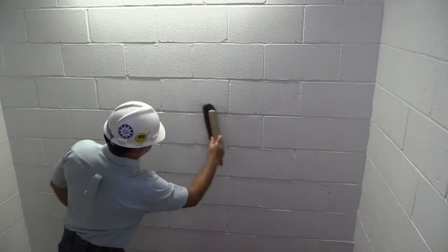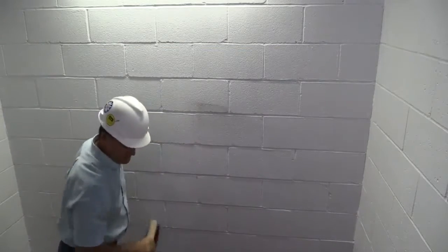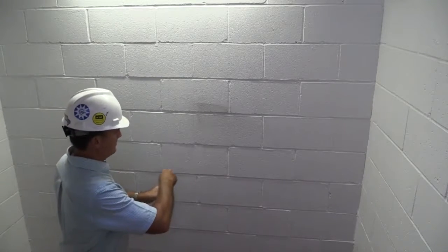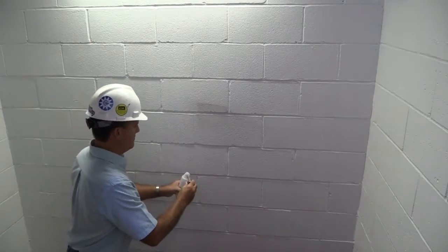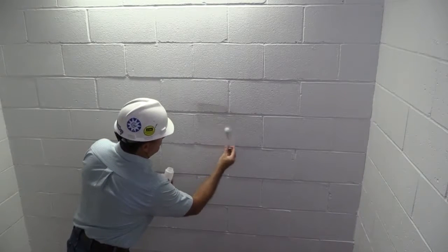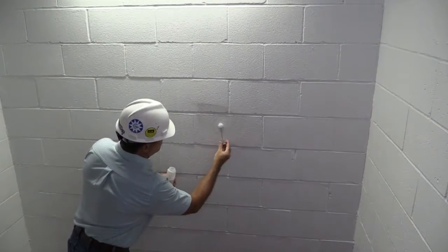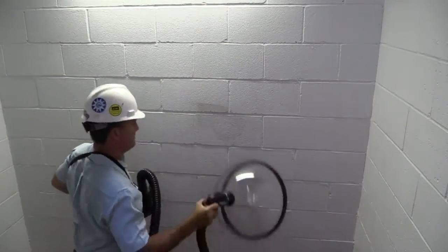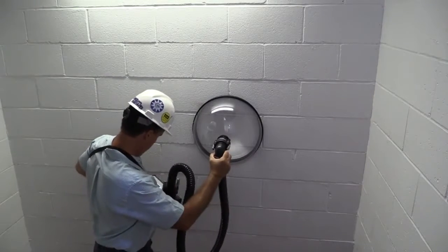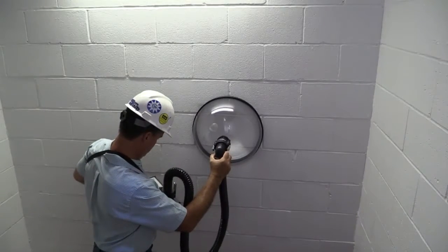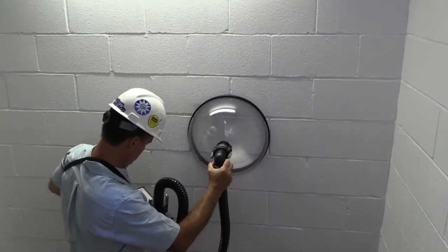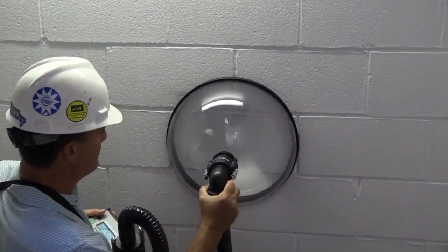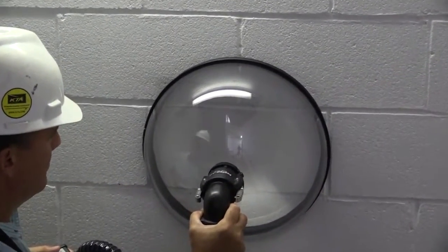To run the test, first, clean the test area of dirt, dust, and debris. The surface should also not be too hot from torching, or frosted, or extremely wet when you run the test. Apply a thin film of the solution over the test area, but don't apply it too heavily, otherwise the solution could froth and foam. Once the solution's in place, hold the dome firmly to the surface. You don't have to push too tight to create a perfect seal because the fan will make up for the difference. Then push the green button once to activate the unit and a second time to start the fan.